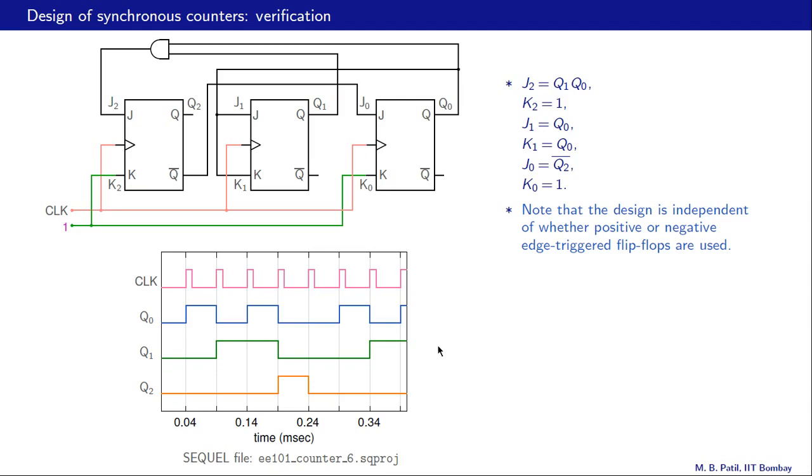Alright, one more final remark. Note that the design is independent of whether positive or negative edge triggered flip-flops are used. So the same connections are also valid if we replace these flip-flops with negative edge triggered flip-flops. The only difference that will happen in the results is that the transitions will now happen at the negative clock edge.